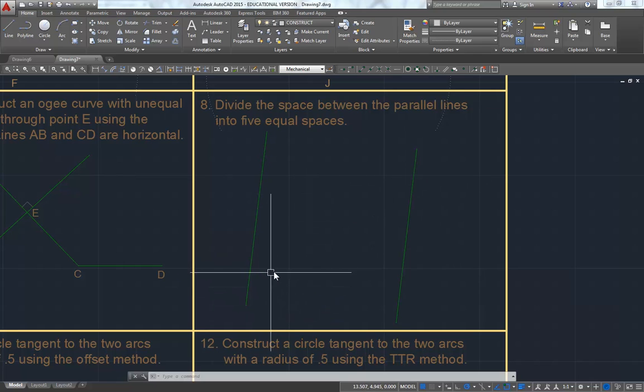And then go 2 inches up the scale and make a mark, go to 4, make a mark, go to 6, make a mark, go to 8, make a mark. Those lines will be exactly equal spaced across, and if you just drew parallel lines through them, you'd have the paper divided. So we're going to do the same thing in AutoCAD. I'm going to draw a line from the end point here to the end point here, and it doesn't matter where you connect as long as you're exactly connected on the line.